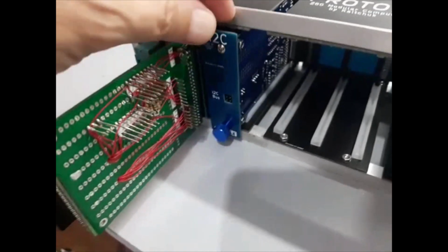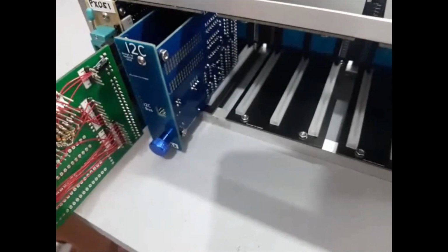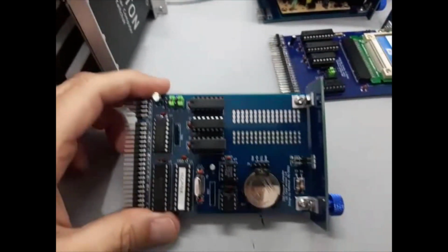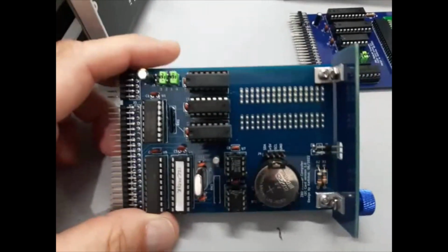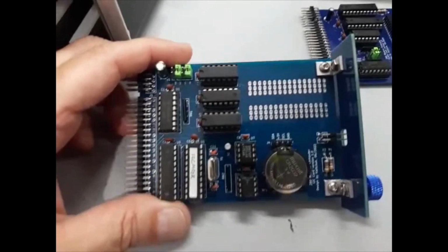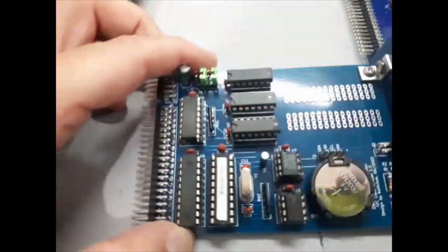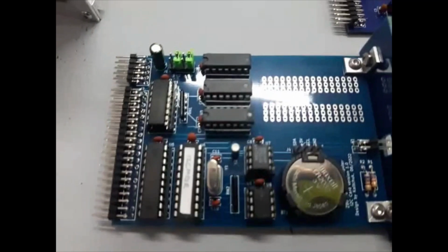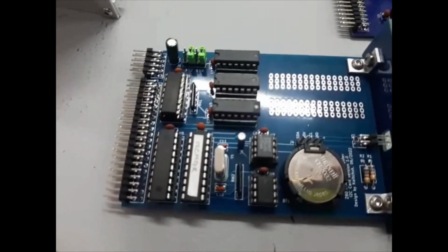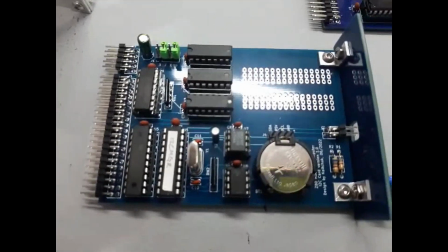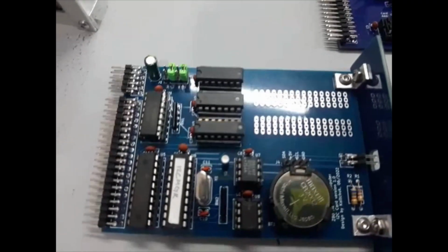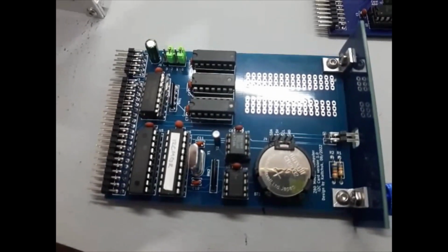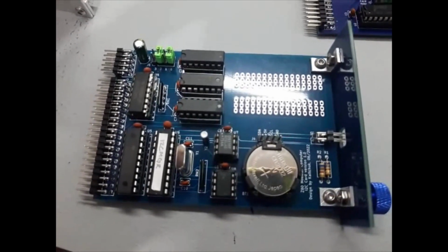Next one is the I2C. So this card is, as the name says, it provides an easy way for the microprocessor to interface with I2C devices. And this is done using a microcontroller. This guy here, this is also an Atmel, but this is AT89C4051. So it interfaces with the CPU, the Z80 CPU, at a high level, and does all the dirty job about the I2C protocol.